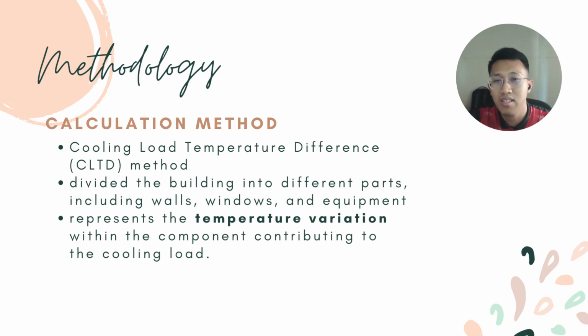By using the CLTD method, we divide the building into different parts, including walls, windows, and equipment. Each of these components is assigned a cooling load temperature difference value, which represents the temperature variation within the component that contributes to the cooling load.